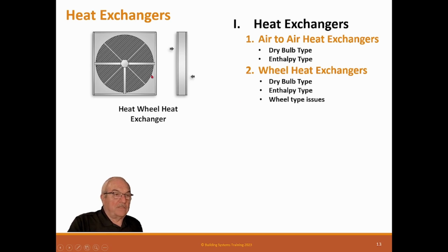Wheel type issues, like I said, if this is coated with a desiccant to make it move moisture, and you let it get soaked for too long, the desiccant has to be cleaned, and the only way it's cleaned is with heat. So normally you have to remove them, heat them up in a furnace or in an oven or something to throw off the moisture. Or sometimes we would bring in heaters, have heating on this side so the heat would blow off the moisture. Either way, the enthalpy wheels can get saturated. It can be a problem.